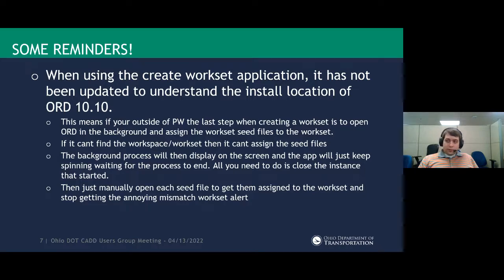This only affects people outside of ProjectWise because you don't have to worry about that with ProjectWise. So when you're running this outside of ProjectWise, the last step of the worksite creation app is to assign your seed files to that workset so that you don't get that annoying workspace mismatch message every time you open the file.